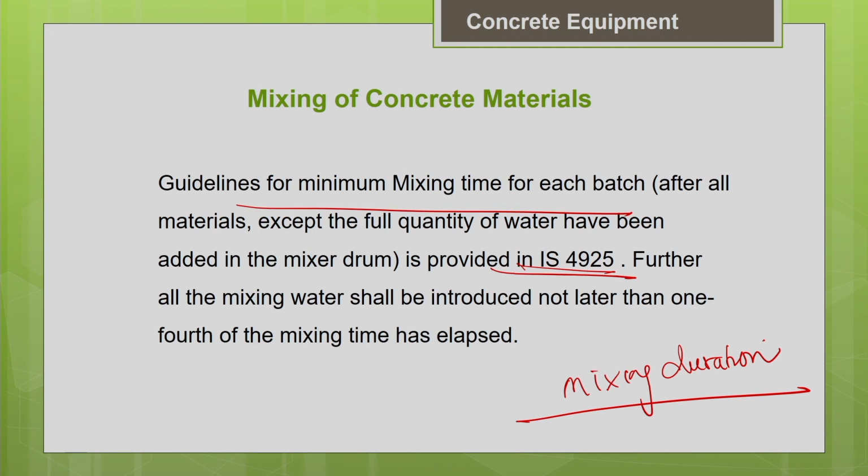The mixing time actually starts after all the materials are added into the concrete mixer machine, except the full quantity of water added in the mixer drum. That means the mixing time starts counting after all the materials are added into the mixer machine, other than the full quantity of water, because commonly you can see that the water is added in parts. You may add some amount of water with the superplasticizer. We break it into parts because we add the water in stages to avoid the loss in workability due to different reasons. That is why it is mentioned like this.